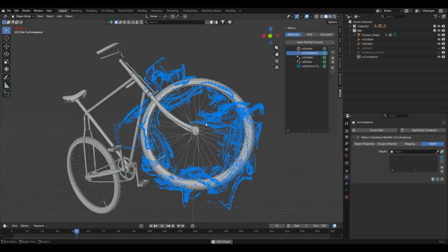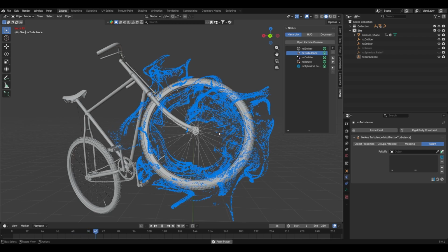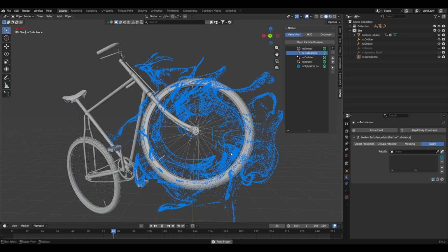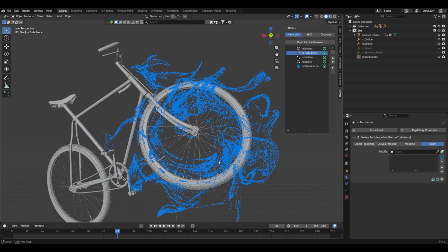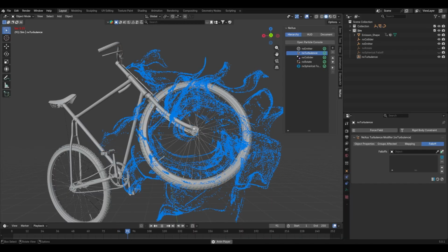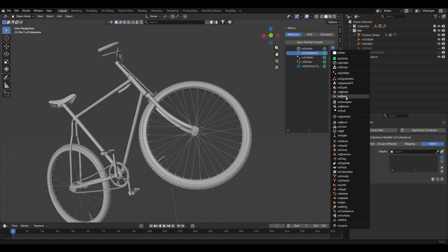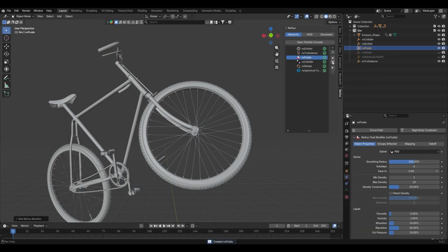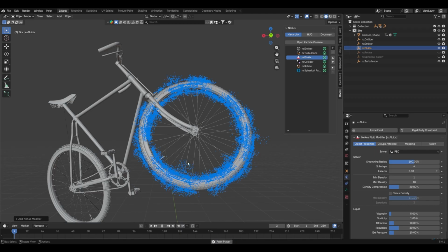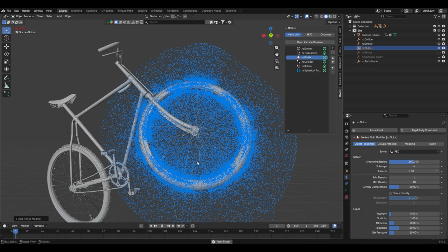But now I want to add some liquid properties into it, this paint viscosity that I want to have. I want to add a Nexus fluid, and I'm going to stay in PBD because this PBD mode is really great for those non-realistic simulations that are really dynamic.